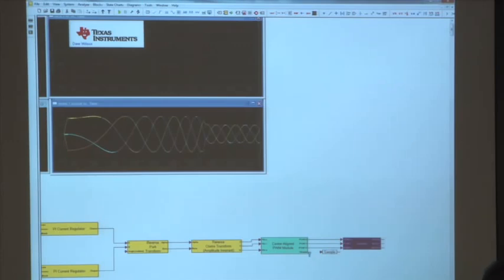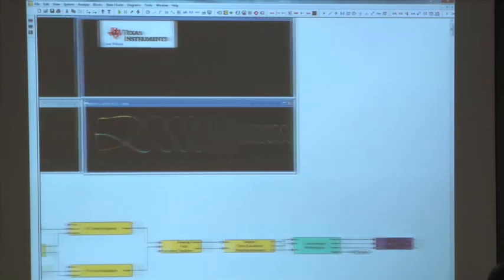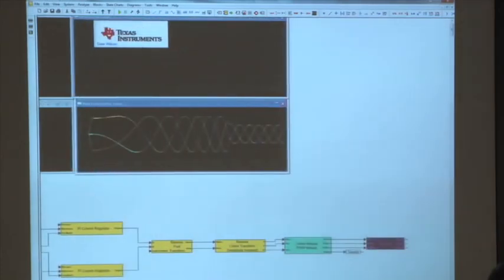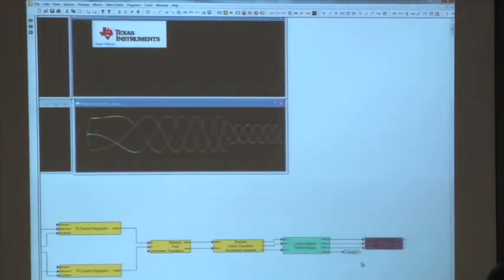Now when I drag the output pin sample on the center aligned PWM module over to the input of that variable, I have now created a variable which has that signal name on it. I can now go back to all these things that had the execute pin on them. What I want to do is click near the sample variable, click and drag so that I select it.